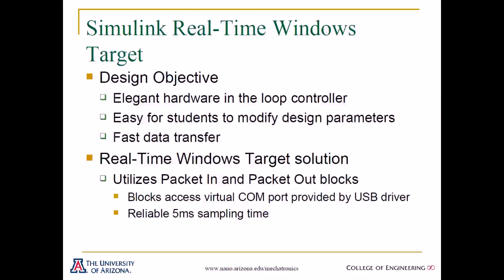We utilize packet in and packet out blocks to communicate with the microcontroller operating the pendulum, and in doing so we've been able to reduce the sampling time down to 5 milliseconds. This faster sampling rate allows us to do more advanced studies, for example collection of frequency response from the pendulum, which was not possible in the previous version of this experiment.